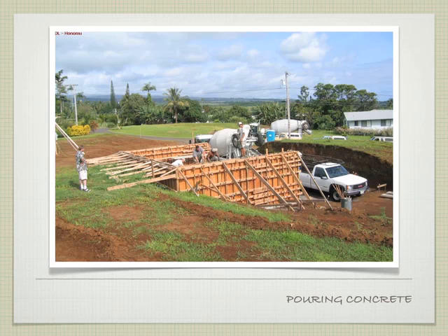But even then, there is a lifespan. One of these sheets of plywood, these nice sheets of formwork, might be used 8 times, and then the surface just starts to deteriorate too badly. So I can pass that around so you can see. It's a really high-quality surface, high grade of plywood. Now, if you were pouring a set of walls just in your house and you weren't planning on reusing the plywood, you might not spend as much money on the expensive plywood. You might use something of lesser quality, knowing that you were going to throw it away. But if possible, you're going to reuse it.